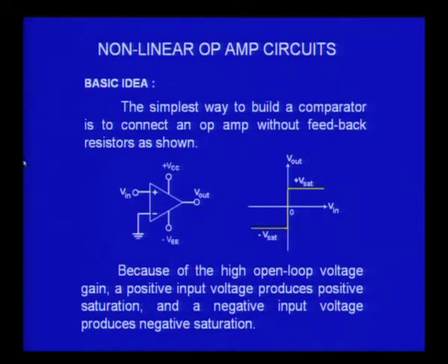If I now make the V in negative by inverting the terminals at the power supply input source and then keep increasing from 0 in the negative direction, you would find that because it becomes less than the positive inverting input, the output will go to minus VCC, because now in magnitude the input corresponding to the inverting input is larger, and therefore the output goes to minus VCC.